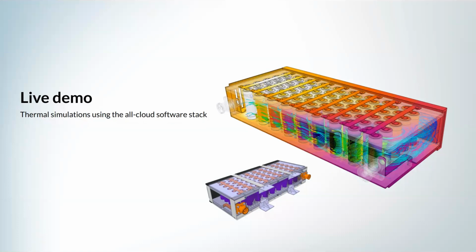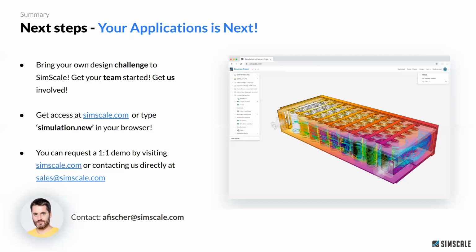So what I've shown you in the live demo simply is that the setup is very similar if you're running a body fitted or if you're running an IBM simulation. There are also great use cases for running body fitted simulations if you want to resolve, for example, flow channel details in a CFD analysis in very much detail. But for the thermal behavior, running IBM analyses, specifically early in the design process, is very helpful and very easy.